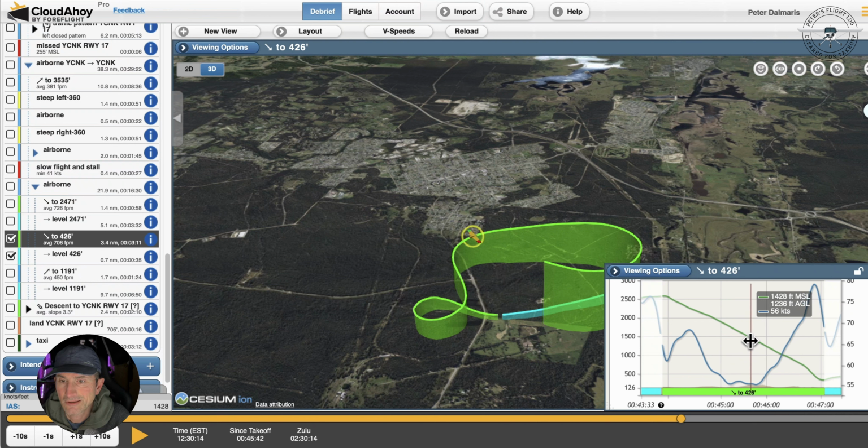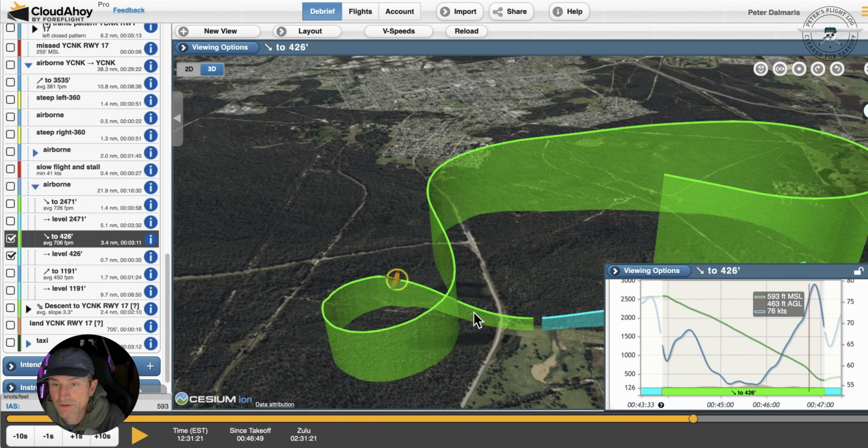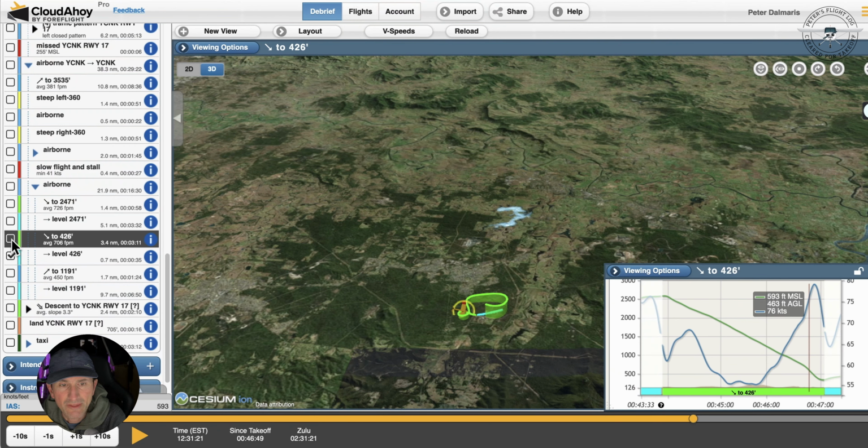But again, the instructor, that's Phil, emphasized the fact that we don't have to stick to the glide speed when we are attempting a forced landing, especially if we know where we're going and we know that the plane has enough altitude and energy to get there. So if we need to descend faster, we just lower the nose and descend faster in order to make sure that we are in a good position when the time comes. So that was cool. And then we turned back.